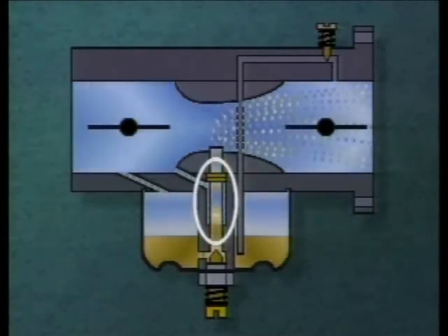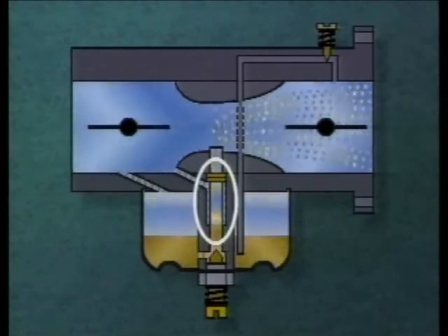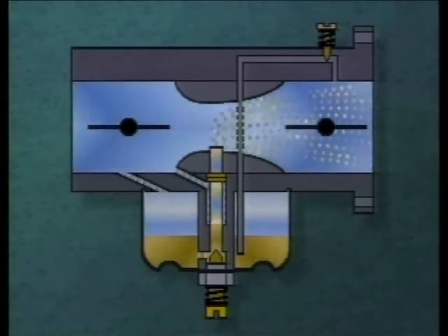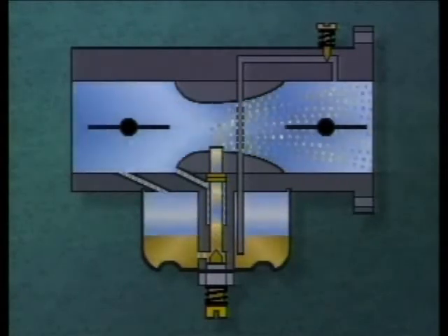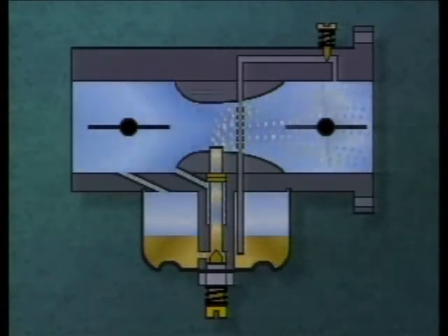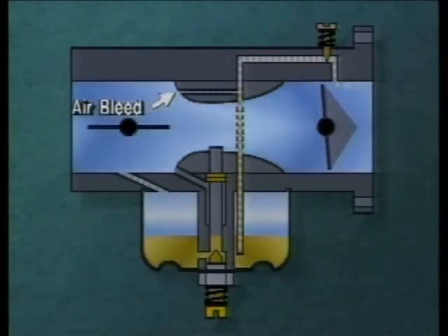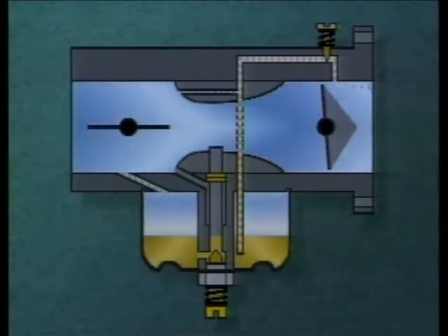Since it's the gasoline vapors which actually burn, this improves the engine's performance and also offers low pressure relief under no-load conditions. An air bleed can also be added to the idle system to provide similar benefits, as well as preventing extremely rich running at no-load idle speeds.